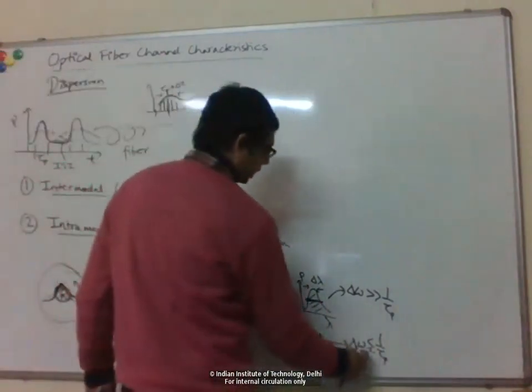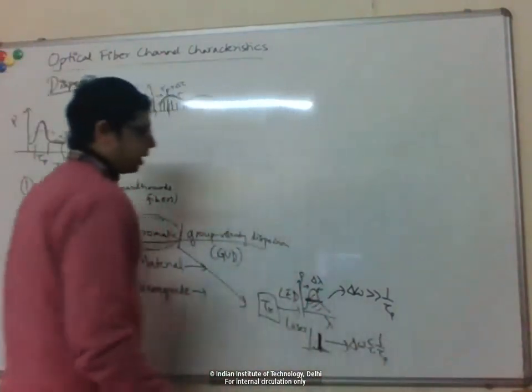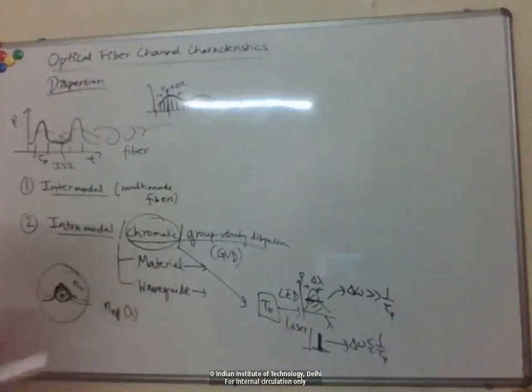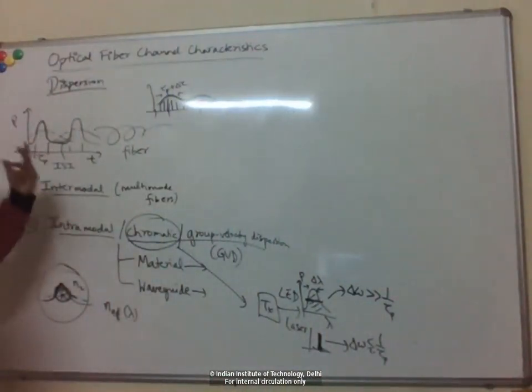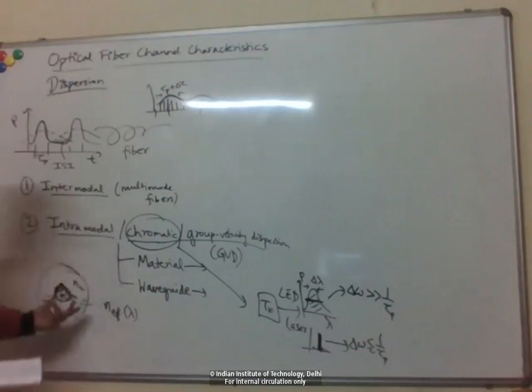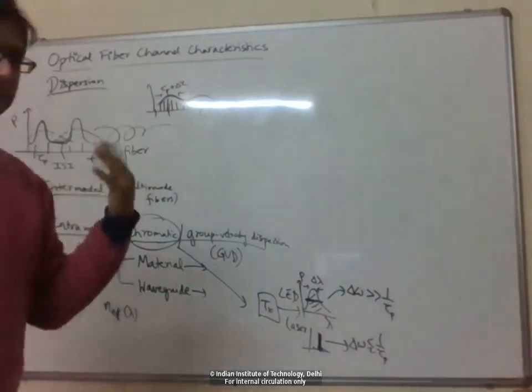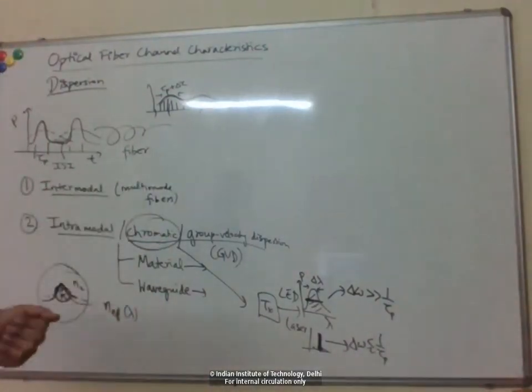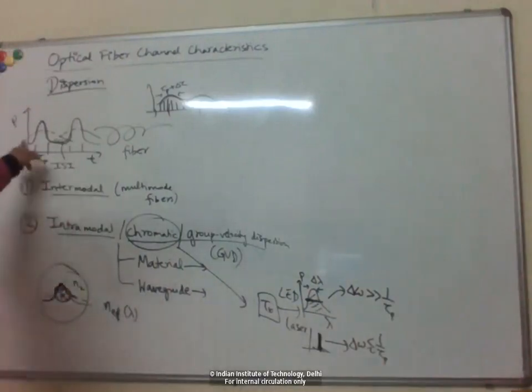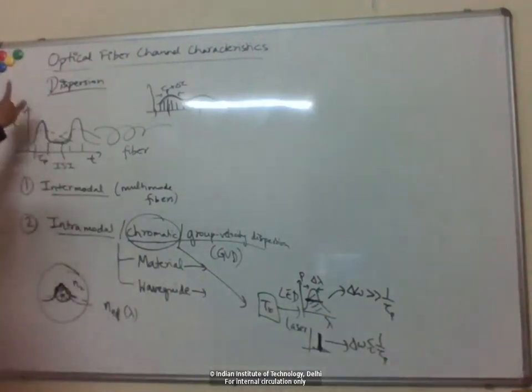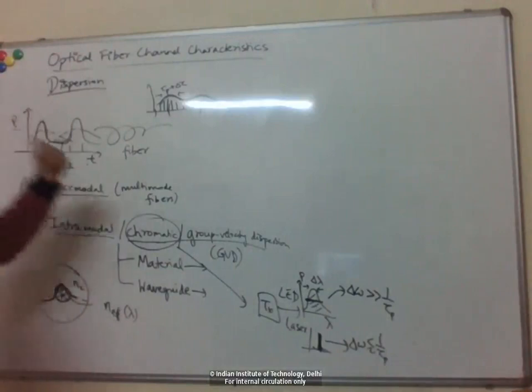So the spectral width is negligible, and the frequency components in your signal are just coming from the mathematical fact that as soon as you have a pulse in time, that automatically means that you have some finite spread in frequency, right? So if you take the Fourier transform of this pulse, in the frequency space you get a spread which is 1 over tau.